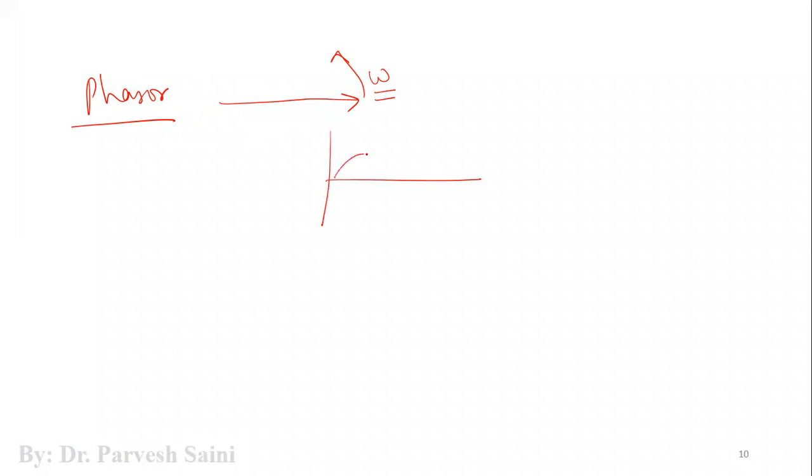So in this lecture we have understood about phasors. A phasor is basically a rotating vector represented with a line and arrow, rotating anticlockwise with some angular velocity omega. When it rotates with this speed anticlockwise, it produces a sine wave. Alternating currents and voltages can be represented with the help of phasors. We can represent two alternating quantities, which will show the lead or lag nature of the quantities. We have also seen how two phasors can be added or subtracted with one another.